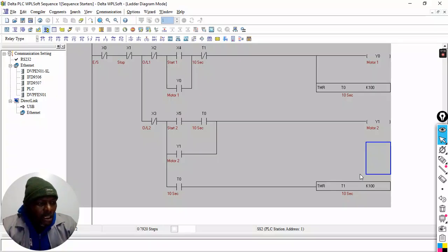So if you go on, it says after a further 10 seconds, motor 1 stops, meaning after 20 seconds. That's what it strictly means. If we go down, the text basically says that. Now, a stop button, which you've dealt with, emergency stop, which you've dealt with, or overload. I refuse there. I changed that by force because I will not allow an illegal scenario to persist. Each motor must have its own overload, so I will not accept one overload.